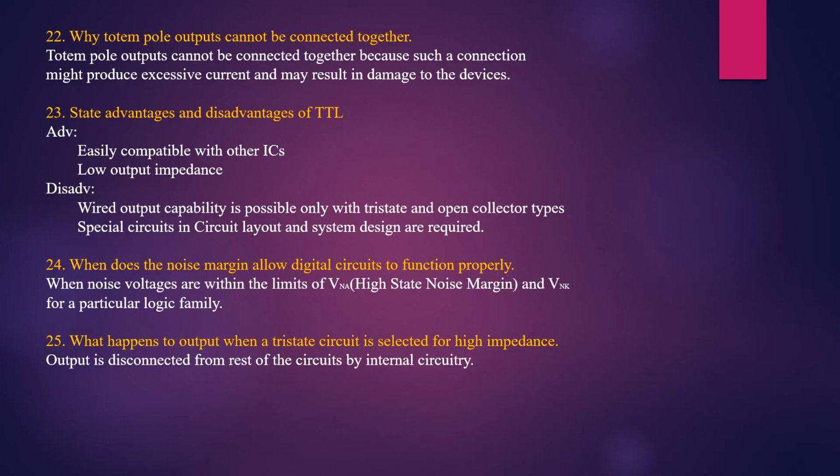23rd question, advantages and disadvantages of TTL. The advantage is easy compatibility with other ICs and low output impedance. The disadvantage of TTL is that wired output capability is possible only with tri-state and open collector types. And special circuits in circuit layout and system designs are required.